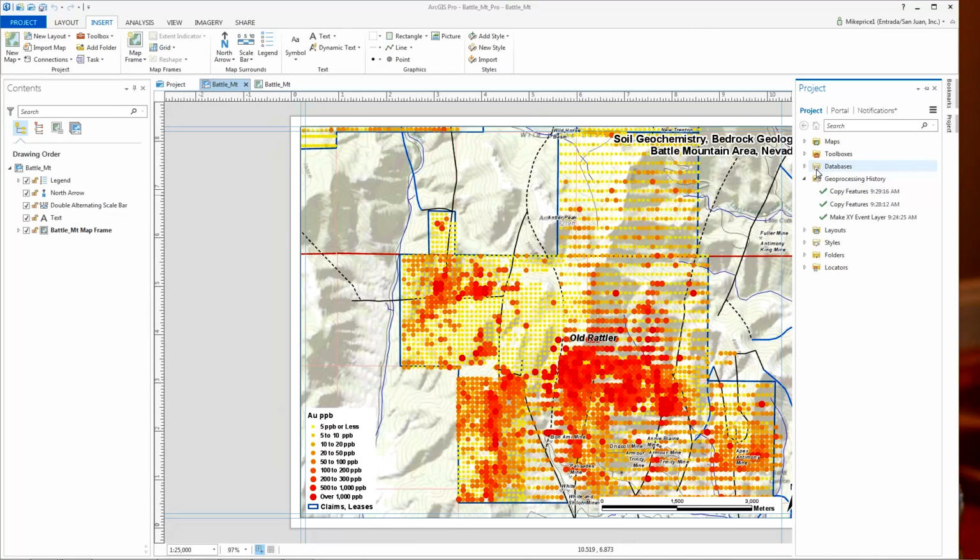How have you found it? What I've been doing so far is repairing them one at a time. The way this data spreadsheet came in, the naming conventions were such that I couldn't repair them all at once. But one of the things I want to experiment with is to make sure that when we repair one, it'll fix all of the other broken links to layers in the same geodatabase. So I don't have a final answer for that. You saw me fix it 5 times, because I had to respect different naming conventions. But I would hope that eventually we'll get to a global repair, or at least a geodatabase-wide repair to fix broken links.